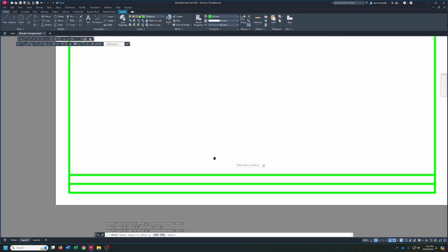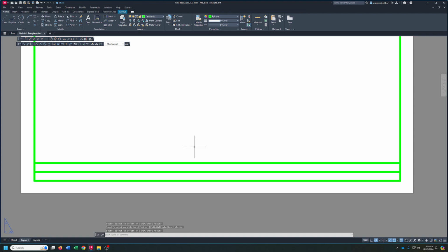And we'll zoom in. Okay. Now, we're going to offset this one to, it's actually 1.98, but 2 works just as well. There we go. And I'll just trim these 2 off. Okay. And we'll trim this one off here. All right, our next offset is also going to be 2. Offset, and it still should be set to 2, so we'll go 2 more. And that one's also going to trim off right here.